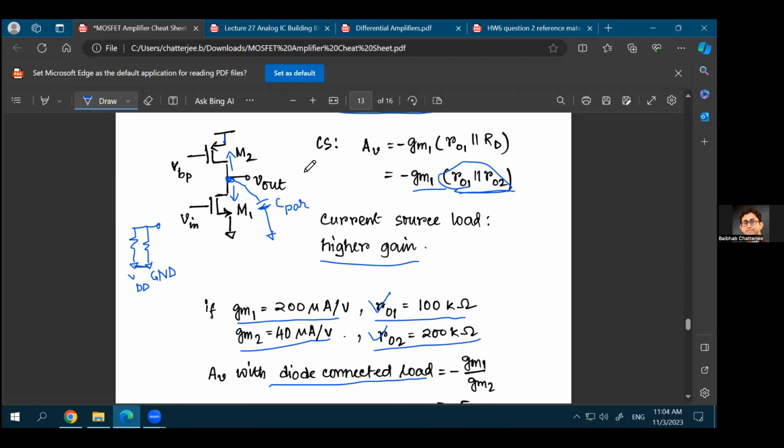Now, where your point becomes relevant is that as you are making the devices smaller and smaller, if you are not able to get enough gain out of these devices because of multiple non-idealities, then it could be possible that your signal will become smaller and smaller. And then your noise will start happening. So, of course, you have to keep this into consideration, that your SNR does not degrade too much.